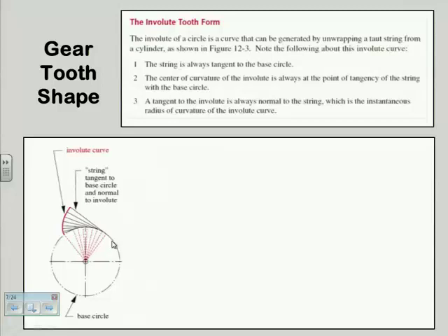And the teeth are guaranteeing me no slip, and they're also not introducing any error into the ratio, as did the old-fashioned gear teeth that I described out at Sturbridge Village, where there are lumps of trees stuck into a big wooden disc to turn the saw in the mill and whatnot. And so you got a peg and a peg between two pegs, and it's rattling around with a lot of backlash and so forth. And it's perfectly fine for sawing wood, but if I want to try to drive my cam in time with my pistons, I don't think I want all that error in there. So I want to have a nice shaped tooth so that I keep a constant ratio and don't let things get out of phase. Okay?